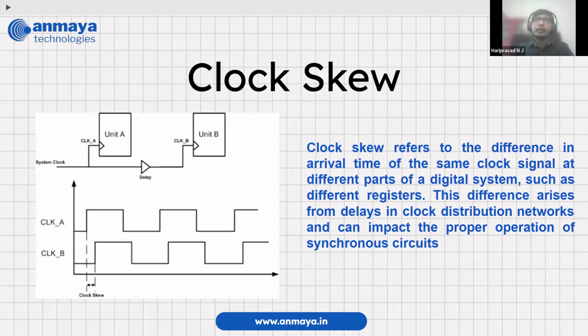Okay, so another major issue is skew. In your FPGA, the flip flops are not very near to each other. As we were discussing yesterday, there are a lot of switching matrices, and especially the clock doesn't go through the data path. There is a separate clock path and data path. We usually say dedicated clock path.